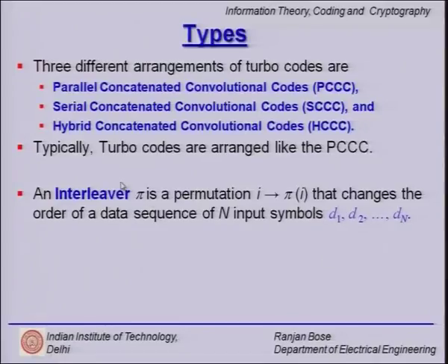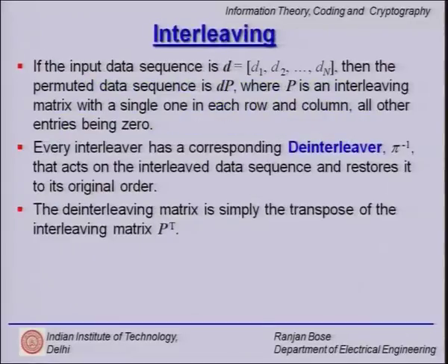Earlier, interleavers were used to ensure that block codes can work where we have a run of errors, burst errors, that happen. So, interleavers were used to separate out the burst errors into random errors, and then the block codes could work. Here the interleaver is being used for a very different purpose, as we will shortly point out.